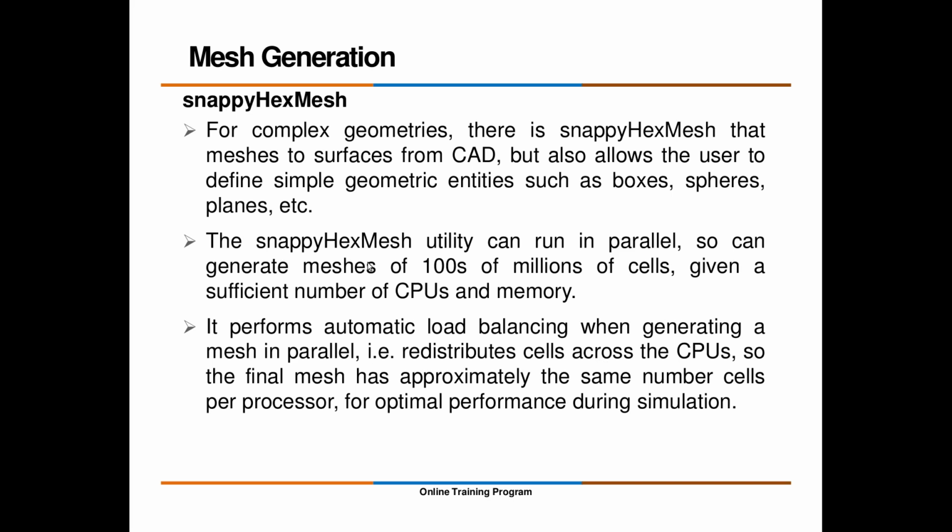The beauty of snappyHexMesh is that it runs in parallel, so that is its strength. Even mesh generation you can handle in a parallel computing environment. Why is it required? Let's say you have to generate a mesh on an entire car, an SUV, where you are expecting something like 30 million or 40 million cells. Then it is not possible to create a mesh on a single PC. For that purpose we require a parallel computing environment, and we create a very sophisticated mesh. And I have seen this snappyHexMesh at ESI.